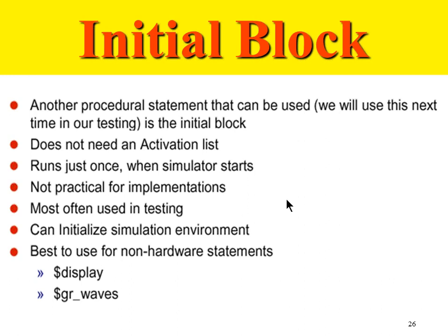The basic program that it has to run when it starts up. So what would we call that condition? Initial conditions or reset conditions. Reset condition, right? So when you power up, the board goes into a reset state. On reset, there is some program that gets executed. In this case, let's assume the program is blinking the LED five times, on off, on off, on off. So there is some logic that I have to execute on the board on reset.